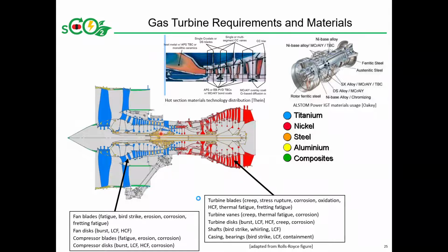You're going to have roller bearings supporting the various shafting in the turbine. Coatings are going to be very important, especially in the high temperature stages of the engine. In the most modern engines, you're going to have internal blade cooling to allow the blades to operate, and that works in conjunction with various coatings that you would apply onto the turbine blades and vanes.